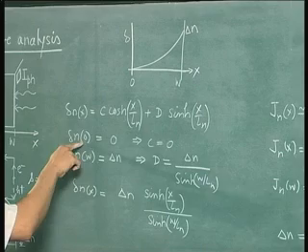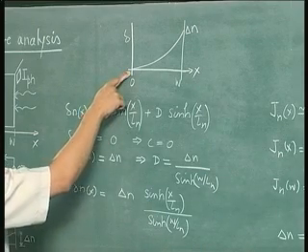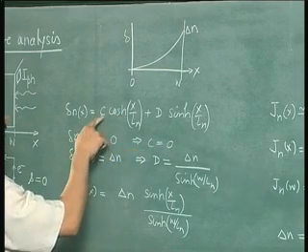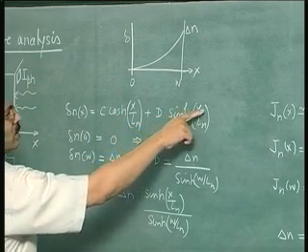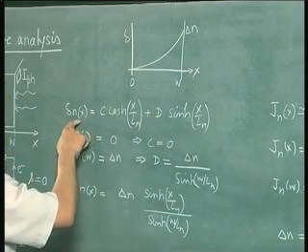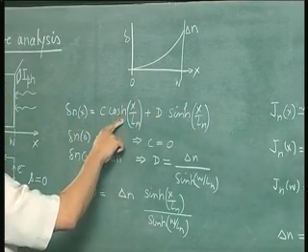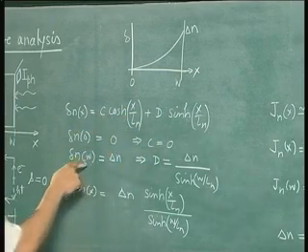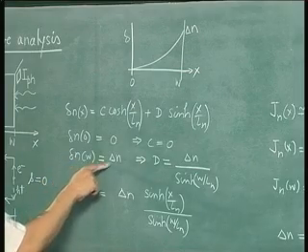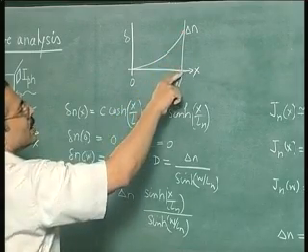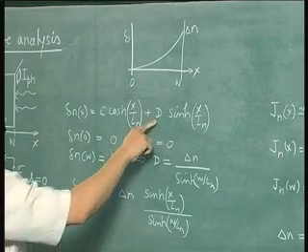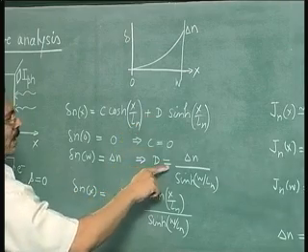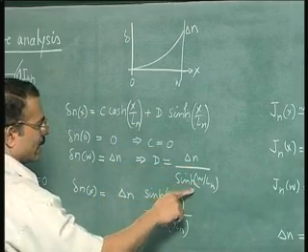Now the value of delta n at x equal to 0 is 0, as shown here. So if you substitute this condition here, you will get the result that C should be equal to 0. This is because when you put x equal to 0, this term will vanish, the left hand side is 0, but this term will be unity, cosine hyperbolic of 0 is unity, so C will remain, so you will get C equal to 0. Using a similar approach, you can write delta n at W is equal to capital delta N, and then since now you are left only with the sine hyperbolic term, you will get from this condition the value of D to be delta N by sine hyperbolic W by ln.